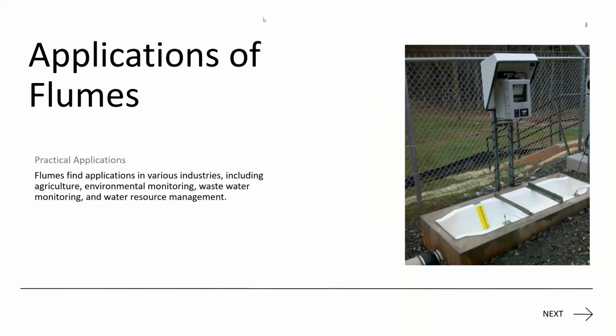Some good applications, we see them in a lot of different industries. So agriculture, the partial flume and trapezoidal flumes were developed specifically for water rights management out west. We see environmental monitoring, so dam seepage, looking at small streams and headwaters, looking at how those affect larger tributaries. And of course, the biggest industry theme is municipal wastewater and industrial wastewater and water resource management.